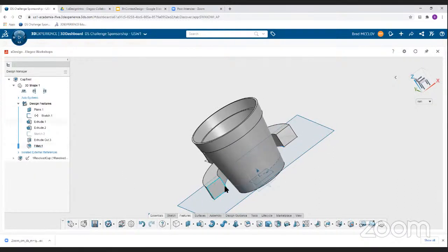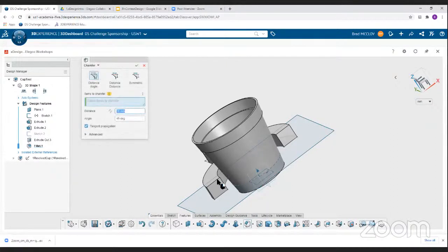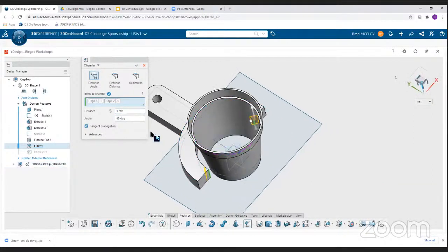Another useful feature is really closely related to a fillet, so much so that it's under the same dialog. We click the little up arrow here. We're going to change the fillet, which is a nice curved edge, to a chamfer, which is going to be a flat edge. I'll click this, and this is screaming at me over here. You can see an error because our distance is too big. Let's go to 3mm. And we're trying to fillet it right off the edge of this, which it didn't really like. Or sorry, we're trying to chamfer off the edge.